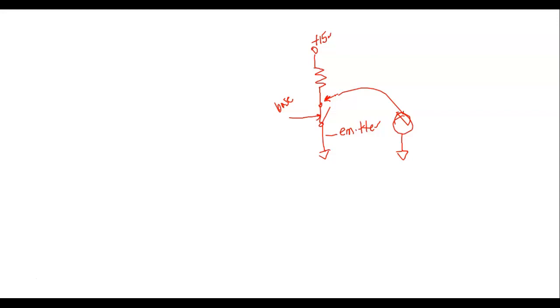If I went over to these light switches that are running these lights and put my meter across those light switches, how much voltage would they show me? Okay, so voltage drop is equal to I times 0. So how much do we drop across a closed switch?